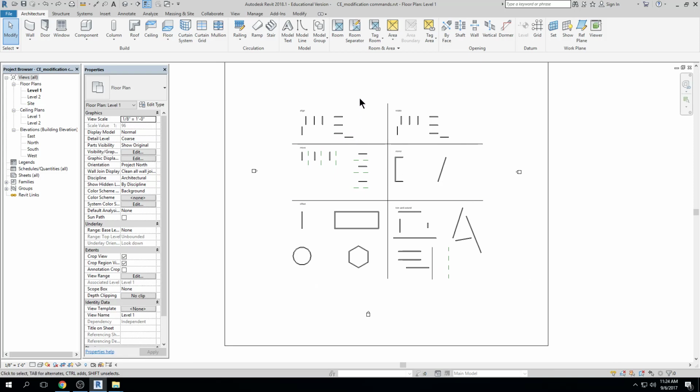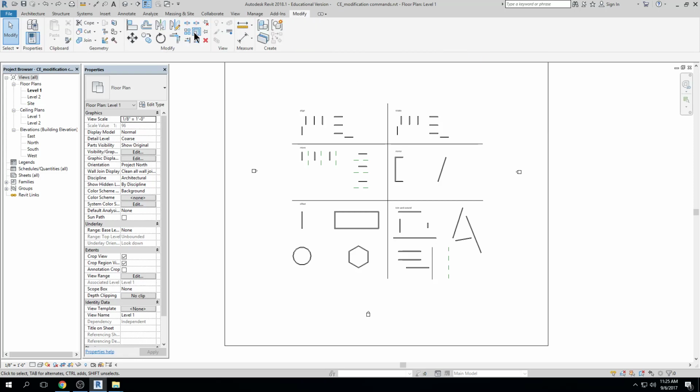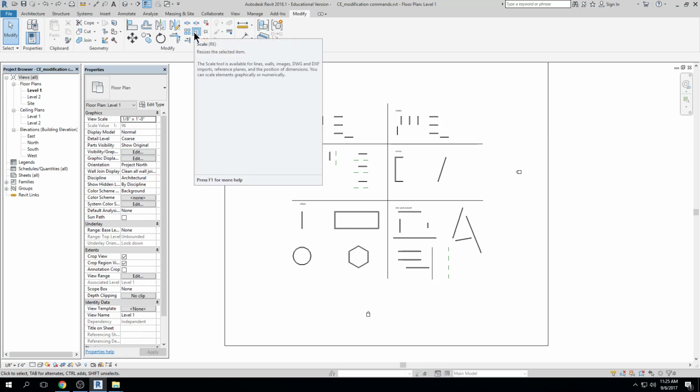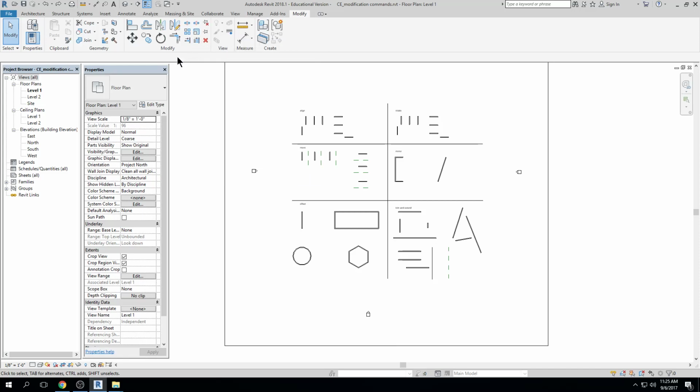There are also a few other advanced ones that I think once we get a little further with geometry creation we can look at. Things like array, and it's kind of the only one I'm thinking of at this point. Let's see, array and scale. What's that? There is fillet, yes. Funny enough, though, I'm assuming you use fillet to square off your corners. Is that right? We're going to use trim in Revit to do that, right? Because I use fillet all the time in AutoCAD to square off my corners instead of trimming and extending. But Revit has combined those into trim.